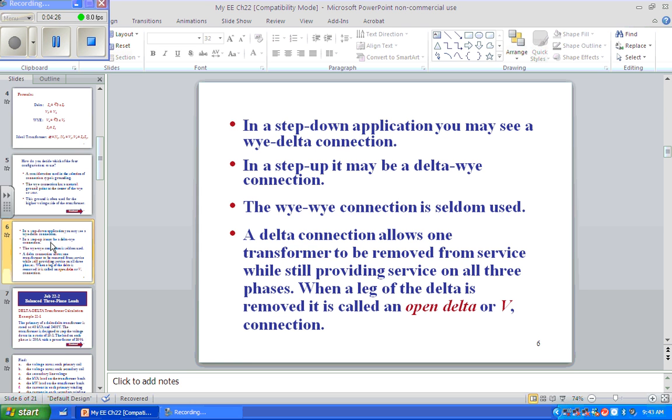So you have to look at what you want, but when someone is selecting the connection system, they're going to look at what kind of load it is. If it's an all motor load with just a couple little very, very few single-phase loads, it'll probably wind up being delta because you don't have a neutral wire running around. Okay.